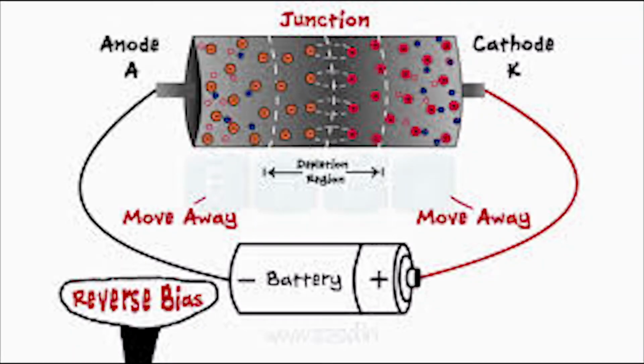The operation of reverse biasing. The positive terminal of the source is connected to the N-type and the negative terminal of the source is connected to the P-type end of the diode. There will be no current through the diode except reverse saturation current or leakage current.